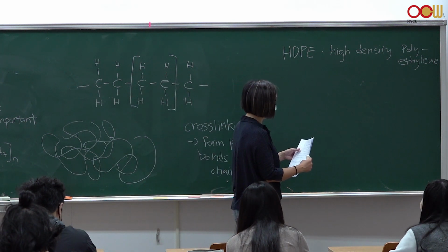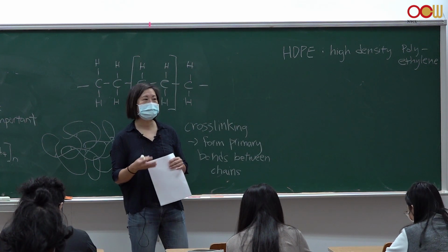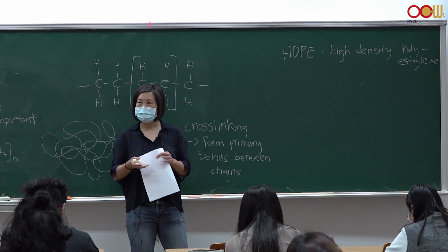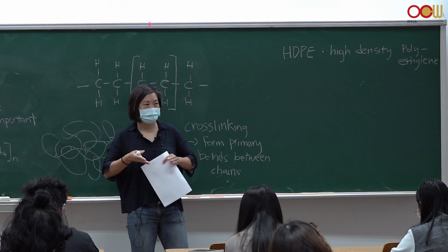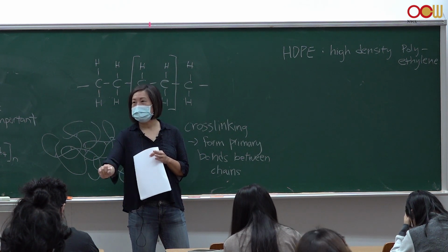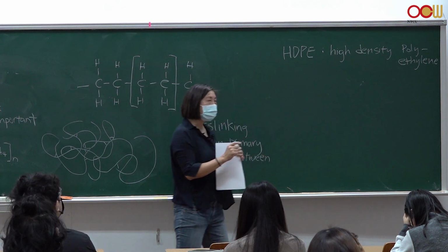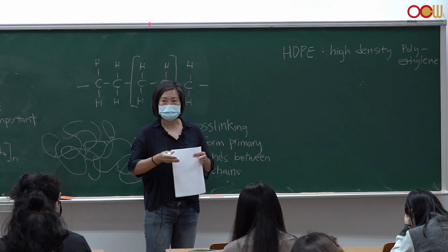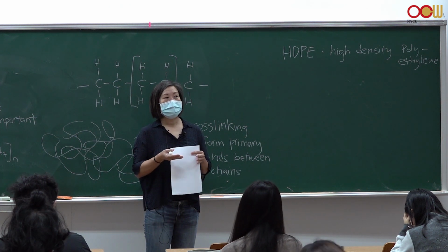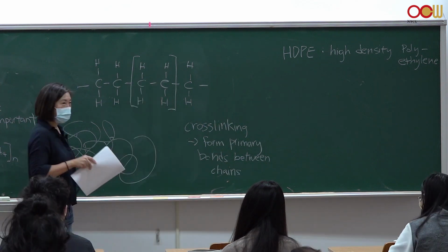High-density polyethylene is formed slowly. So polyethylene, like a lot of plastics, is extruded into its shape. You just push the liquid material through a hole and form a shape, like a fiber or something. And high-density polyethylene is extruded slowly, so it's pushed through that hole slowly. The rate of extrusion allows the chains to line up.